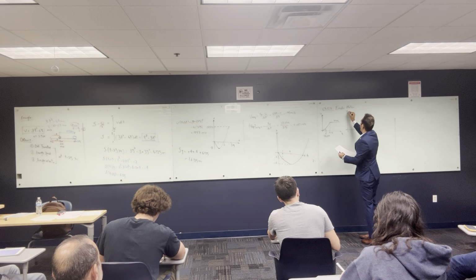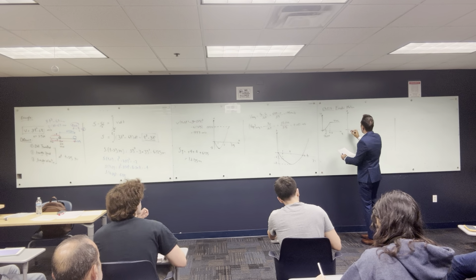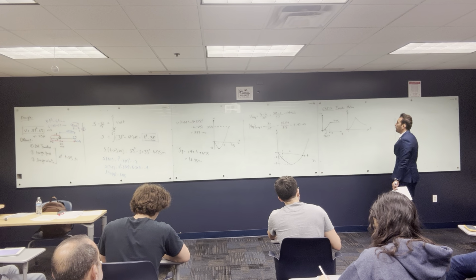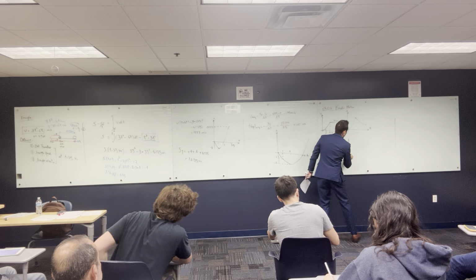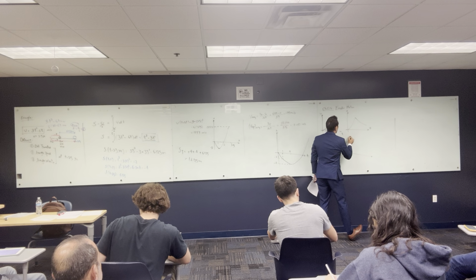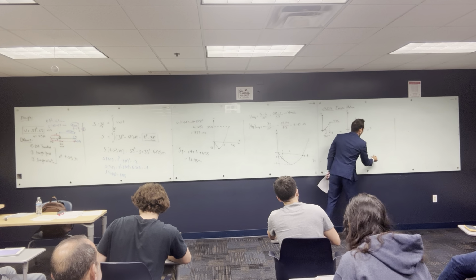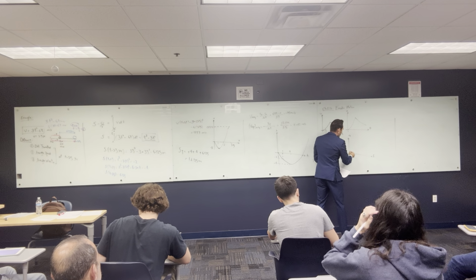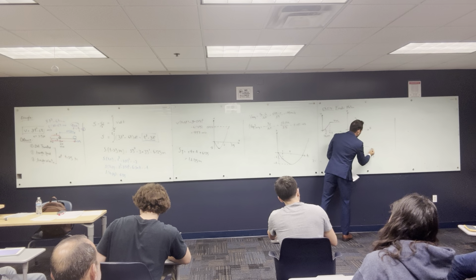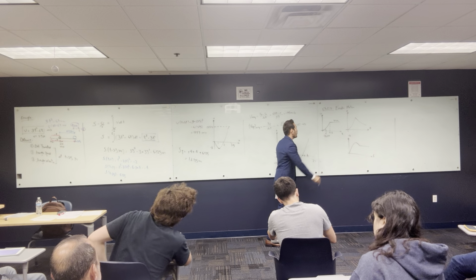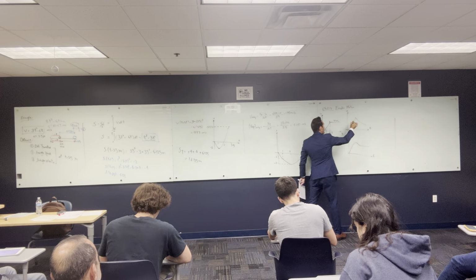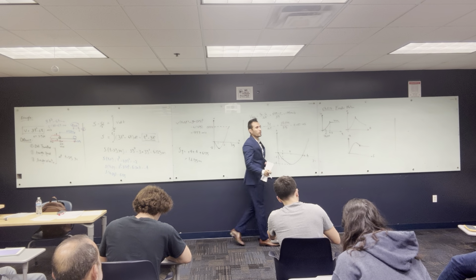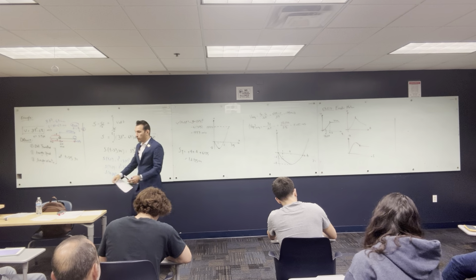Sometimes you can have the acceleration as a function of t. Let's say your acceleration is going up, and then your acceleration is going down. Or, let's say acceleration versus displacement: your acceleration is something like this, and then constant like this. If there is an abrupt change in your function like this, two lines or two curves, that is called erratic motion. You need two functions to describe this motion.